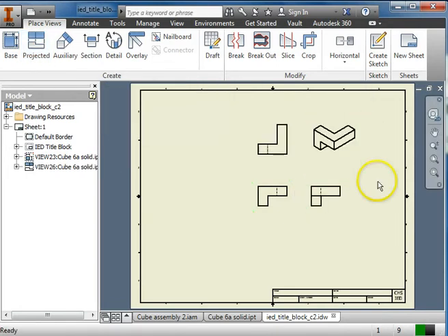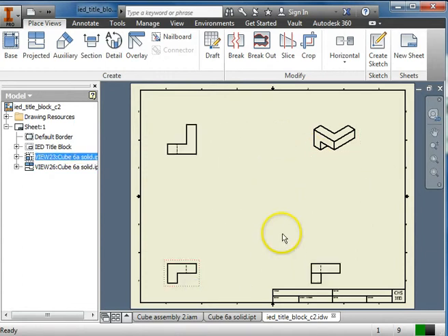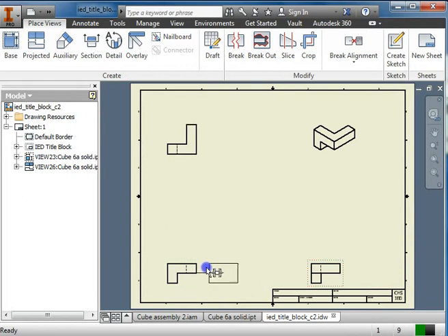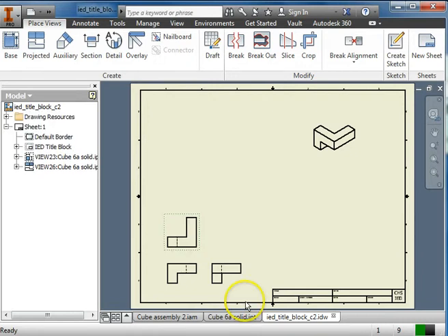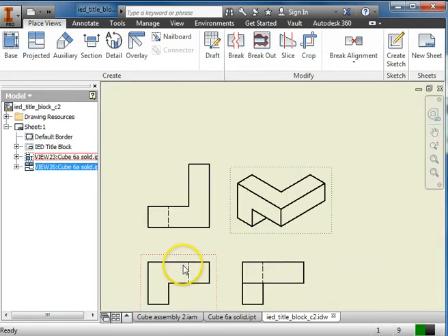Right click, create. Okay, so I can move these around. The front view is always in control of the right and the top view. You're going to have a little bit of space, or a lot of space, to get all of your pieces in. So you're going to need to crunch them in there pretty good. Now you can see I've got one solid block, and I can see the dotted line that represents this part, and then a dotted line here represents this part on back.